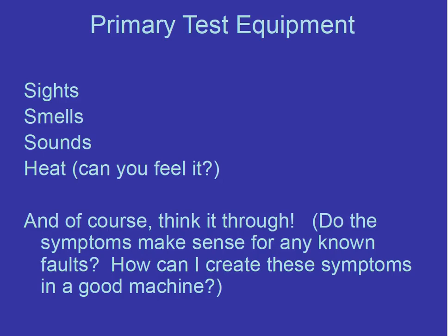without that also you can basically detect if something is going wrong with the circuit by smell, by sound, and sometimes heat, flames basically go up, and you can actually visually see that, and then usually the immediate response is to turn off the power. So check for any exploded or burned parts of the circuits by seeing or smelling them, and look for any loose connection. Check for any ground paths.